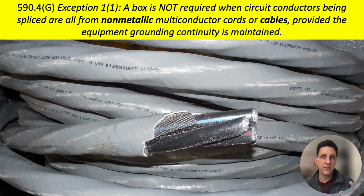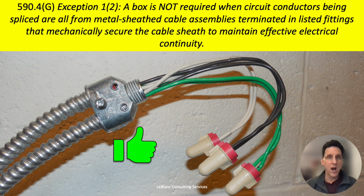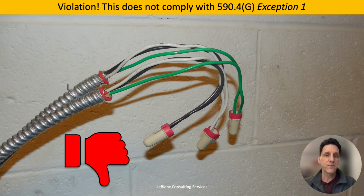Now for metal cables, we have exception 1, item 2. A box is not required when the circuit conductors being spliced, and again, this is for branch circuits and feeders as well, are from all metal sheath cables, terminated in listed fittings, and the fitting will secure the cables to the fitting and bond the cables together to maintain that effective electrical continuity. So again, we got the thumbs up for this. No box needed. Doesn't matter if that's a feeder or a branch circuit. You can splice just like that on a construction site with no box.